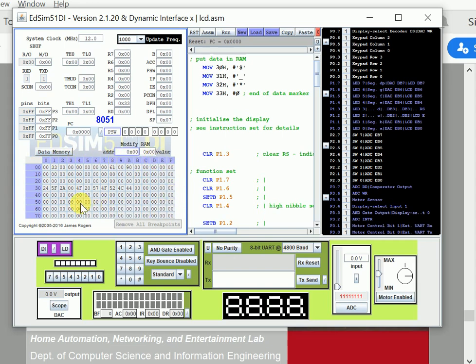And also if you want to write something into the RAM, so that your program can take that value in from the RAM, then you can directly give the address here, at which address you want to give a value. For example, I want to write something at 6000, fine, 6000. At this address, if I want to write a value, you can put any value from here.